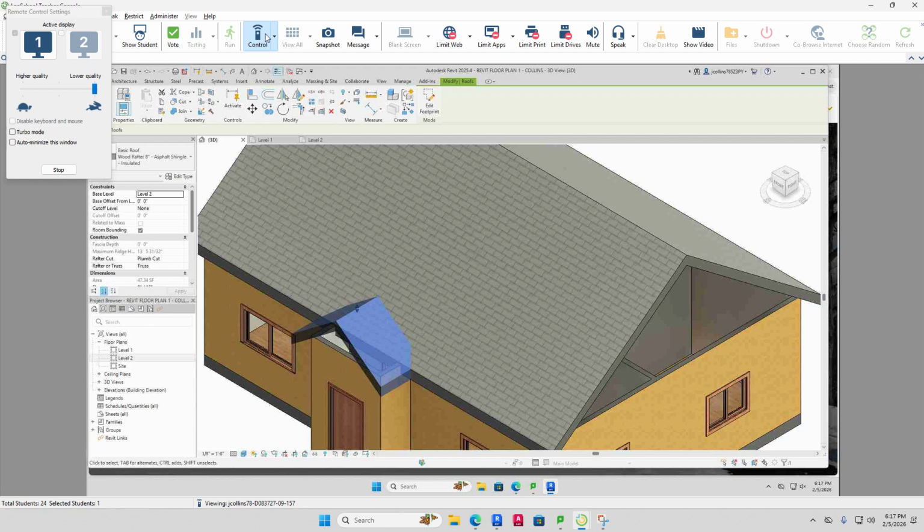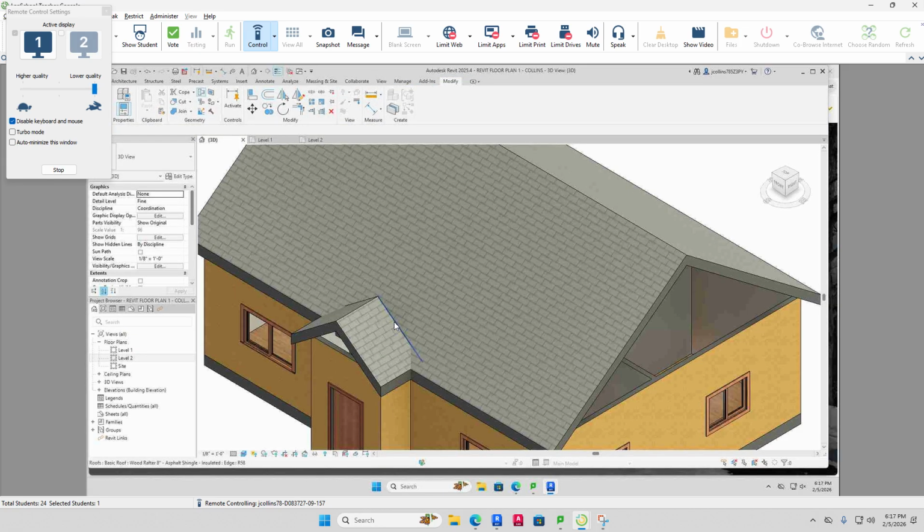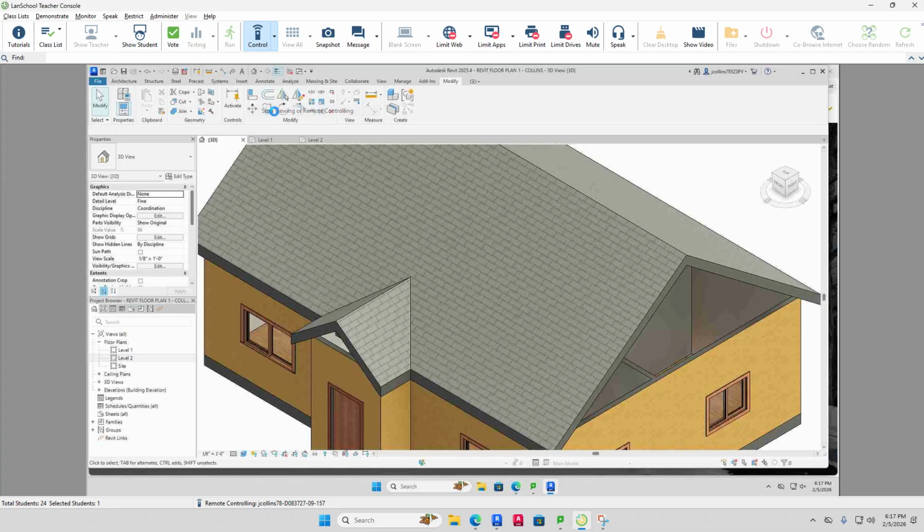And this is what you want to do because I can't display it right now, and I can't really explain it. So I'm just going to go here, and I'm going to go here. When you have this roof selected, you can go to what's called roof join. Now go ahead and click on the edge here, and click on the edge there. Then it joins the roof together, just like that. And then go ahead and save it there, Jennifer.